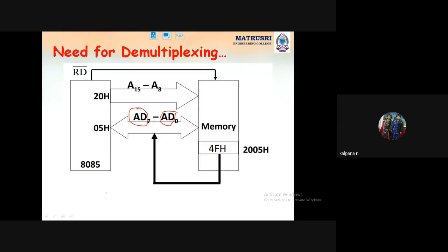That indicates that whenever that pin goes to logic 0, memory will be functioning. That means the processor can do anything with the memory: it can read information and write information into the memory. Whenever that pin goes to logic 1, IO will be activated. So that is easy, because when that pin is 0, memory will be enabled, and when that pin is 1, IO will be enabled.